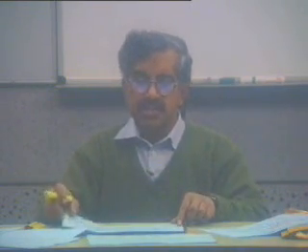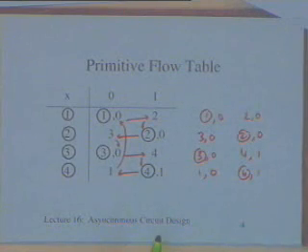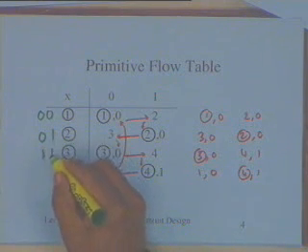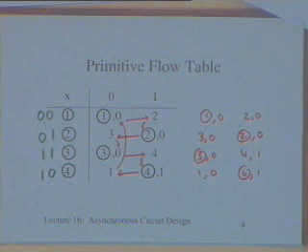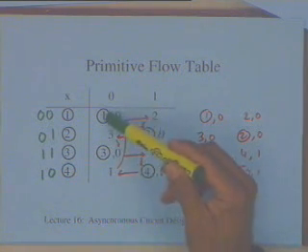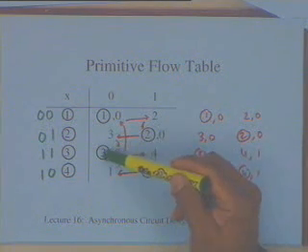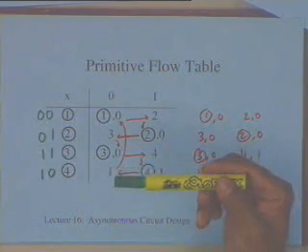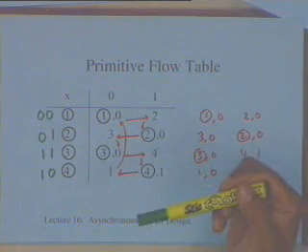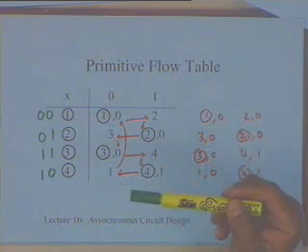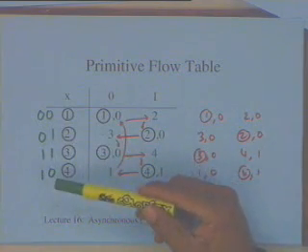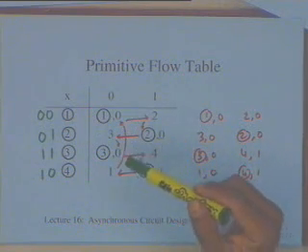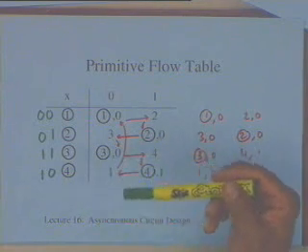So in this particular case, I could have done something simpler. I could have encoded this as 0 0, I could have encoded it as 0 1, I could have encoded it as 1 1, and I could have encoded it as 1 0. Now each time a change takes place, I go from 0 0 to 0 1, from 0 1 to 1 1, from 1 1 to 1 0, and from 1 0 to 0 0. All my transitions, which correspond to the equilibrium states, correspond to only one change of secondary variable. And if you encode it in this manner, it is possible that we will avoid the type of problems we faced. But sometimes, we will of course do a much greater analysis of it.